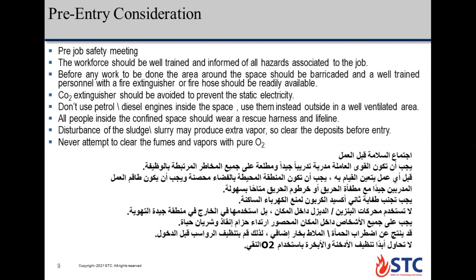Don't use petrol or diesel engines inside the space. Use them outside, in a well-ventilated area. All people inside the confined space should wear a rescue harness and lifeline.